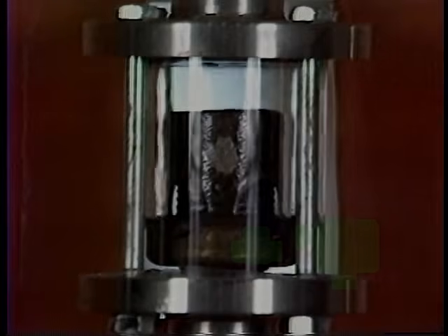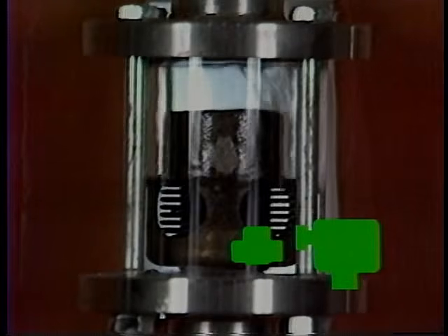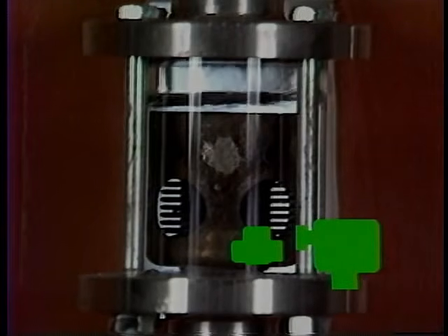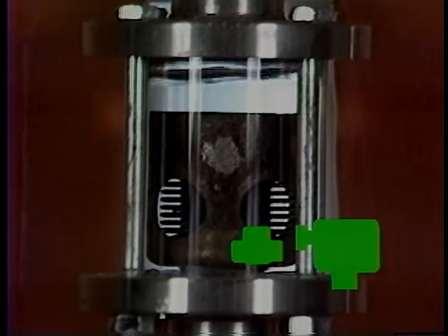One of the first evaluations should concern the amount of live steam lost through the trap when it's new. All trap types condense some steam due to thermal radiation, but live steam is discharged from some types even when new because of the way they are controlled or sealed. The water seal prevents live steam loss through the IB and the primary orifice of the DC. Disc and bellows traps prevent live steam loss by closing in the presence of steam or condensate near steam temperature.